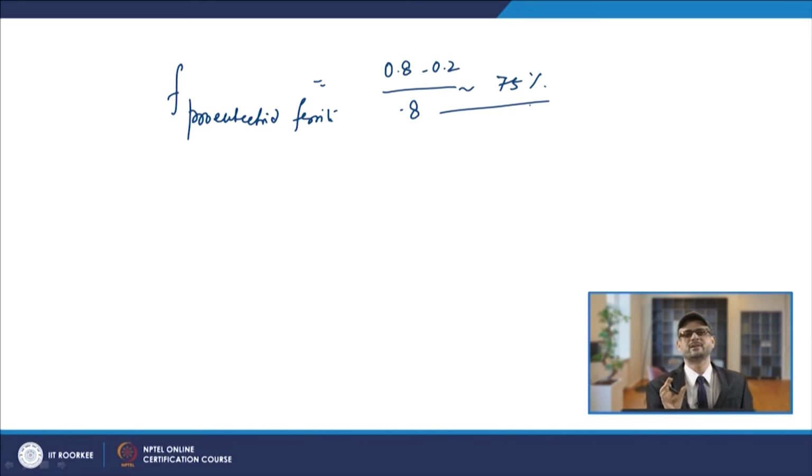If you calculate the eutectoid ferrite percentage, it will be about 0.22. If you sum them altogether, it will be 0.75 plus 0.22, so 0.97. So 97% will be the total ferrite. This way you will have the eutectoid ferrite calculation and the proeutectoid ferrite calculation, and accordingly you can find the total ferrite, which will be 97%.